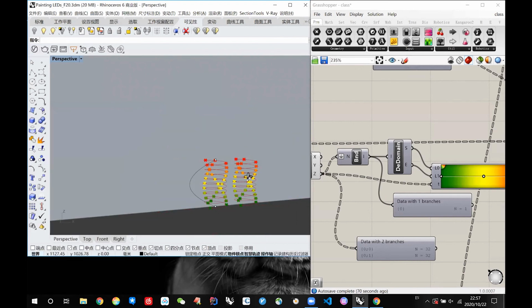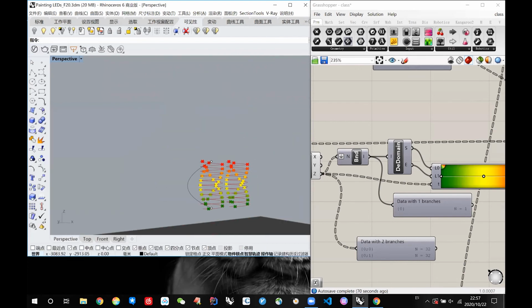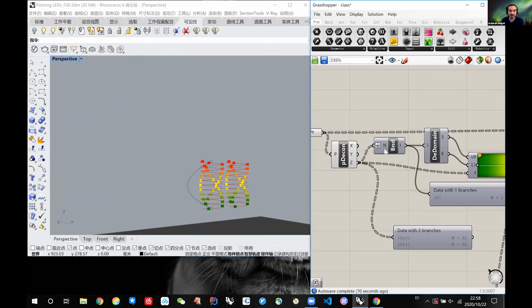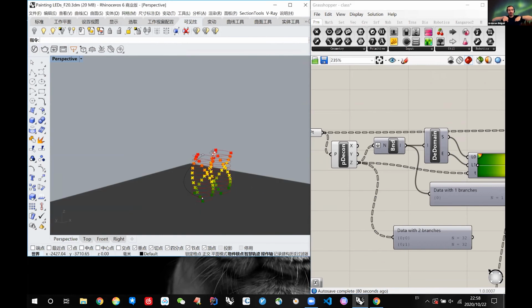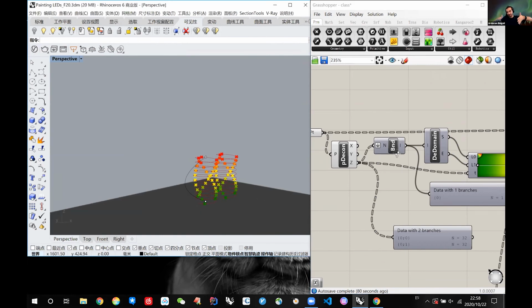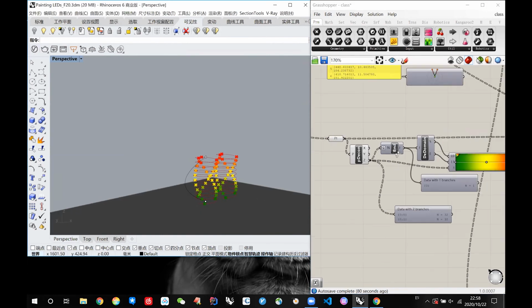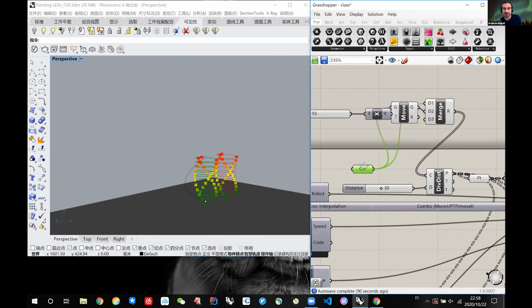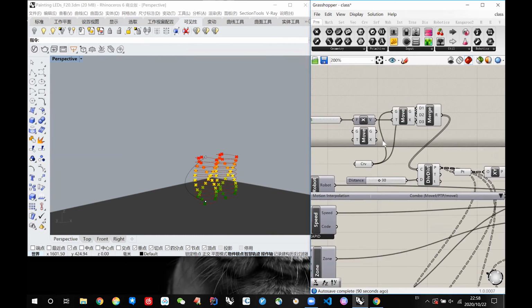Can you see my screen here? Yes. Because the Z value for both of your spirals is actually the same. That's why you have the situation. That's why I actually moved one of the spirals a little bit higher. So do you see that you're moving it along the x-axis? Try to move it also in the z-axis. Okay. So no, you can still keep that move. That's fine. Just add a z vector here.